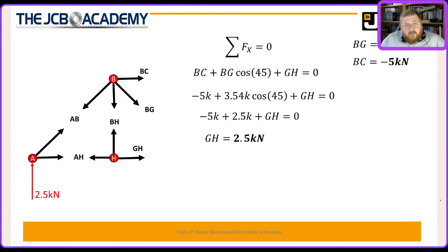Typically with this, you'd be asked to work out the stress in one of the main support members to see if that member can withstand the truss. I have set my class a task to use the method of sections to check 6 of their values in their assignment. So I'm going to repeat this process for another section of the truss, just to make sure we do my 6 and my students can do what they do.